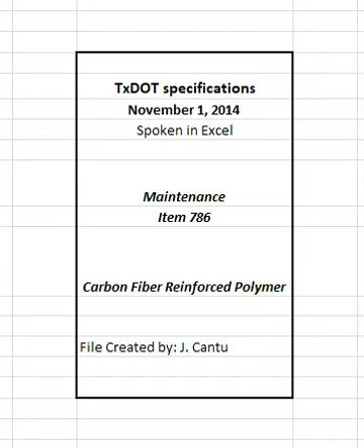Drill holes in concrete using a rotary impact drill when CFRP anchors are shown on the plans. Ensure existing reinforcing steel is not cut when drilling holes. Thoroughly clean holes by using a wire hole brush and oil-free compressed air to remove all drill powder from interior surfaces of hole.